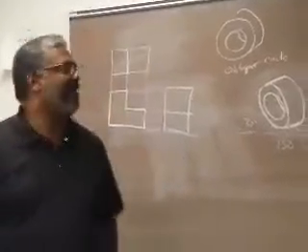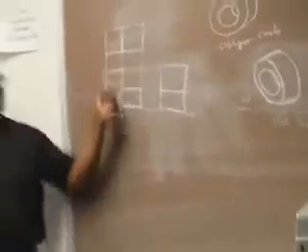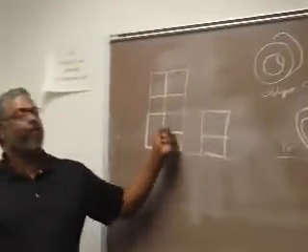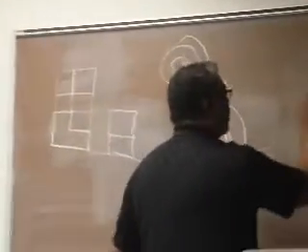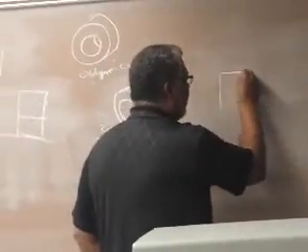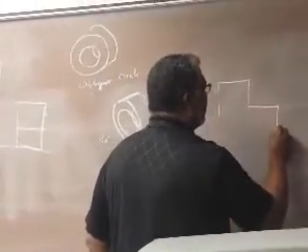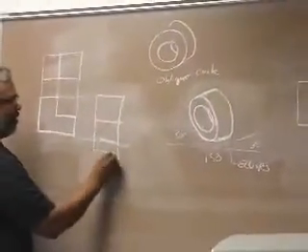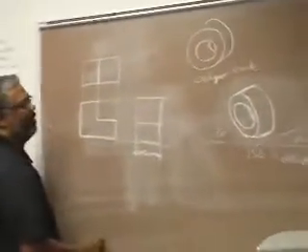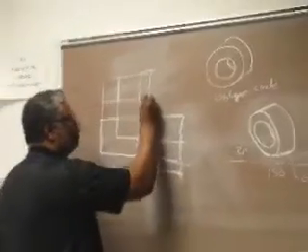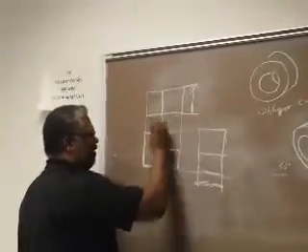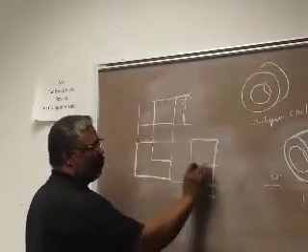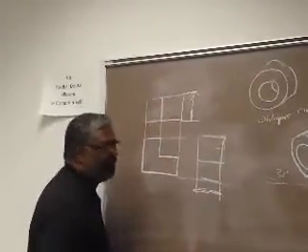So, in this case here, we set this up where we call this the front, because it's the most descriptive. To draw an oblique, I just draw the front as it is, but I got to show thickness. I got to show this depth here of the object. And just like an ISO, lines that are parallel in your orthographic view will remain parallel in the oblique.